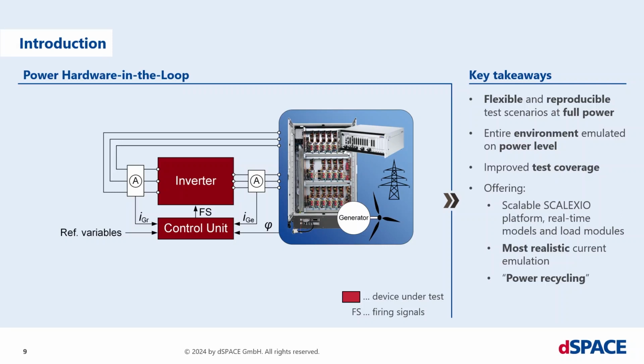dSPACE offers not only the Scalexio platform, as we know that from the signal hardware in the loop testing, but also these load modules to bring the behavior to the power level. And in the next slides, I'm going to show you that we also have some kind of power recycling due to the fact that we are not only emulating the input or the output side, but both of them. We can circulate the overall power flow. But that I'm going to explain in one of the next slides.